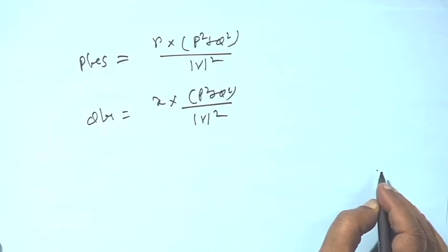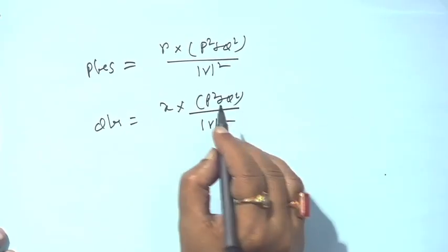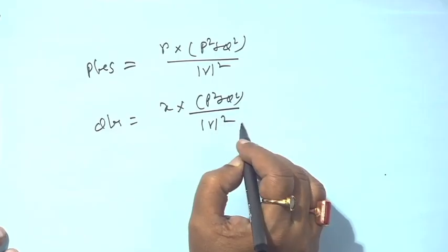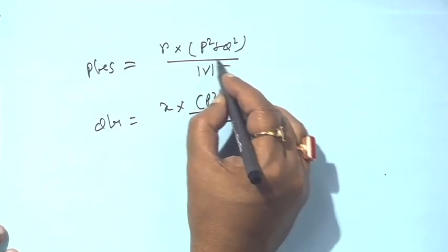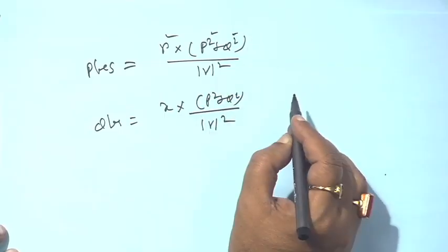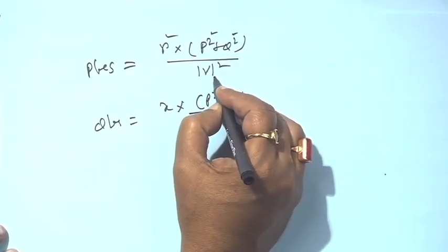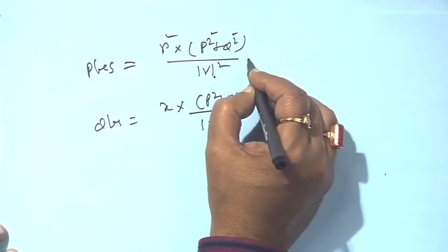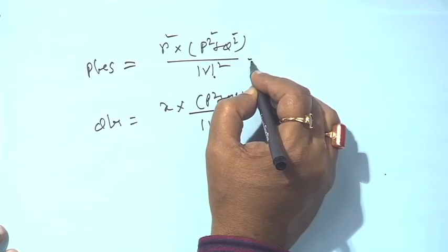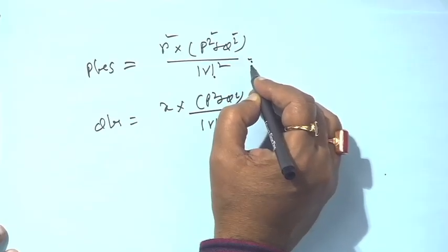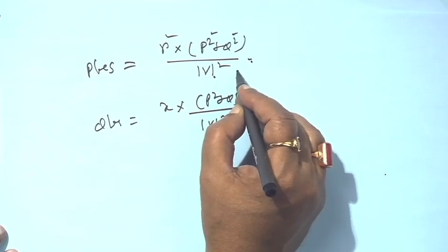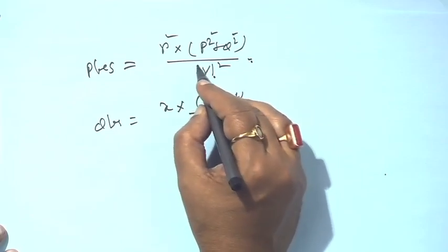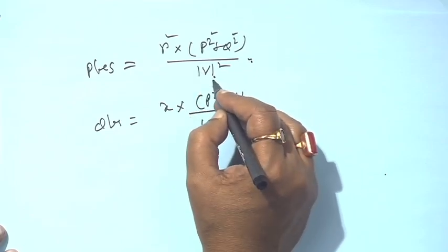Because of the series capacitor placement in the line, the voltage is improving. Although R and X are unchanged, due to the improvement of the voltage there will be a reduction in power loss, but that is quite less. Though not much, it reduces the power losses because the voltage is getting improved.